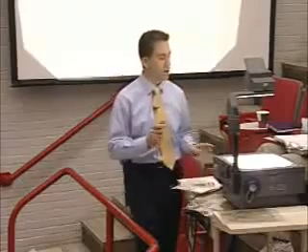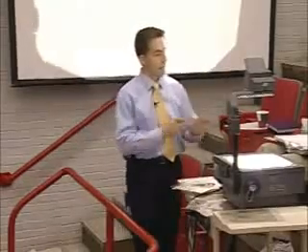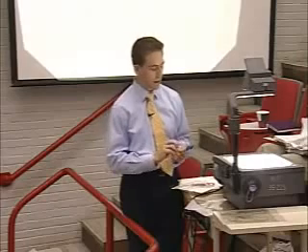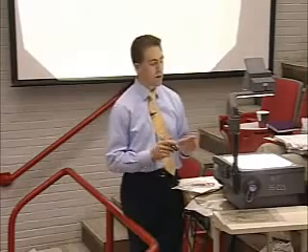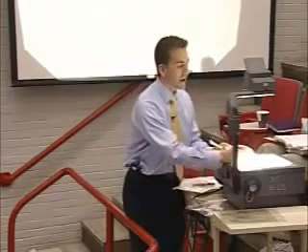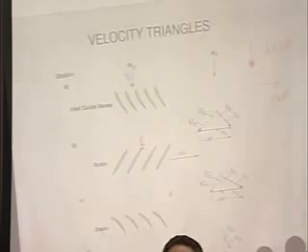Okay, now I want you to do the same things that I do on your handouts. We're going to follow these rules. The first thing that we said to do is check the incoming angle of attack of the flow. From the perspective of an airfoil, this would be the angle of attack on that airfoil.